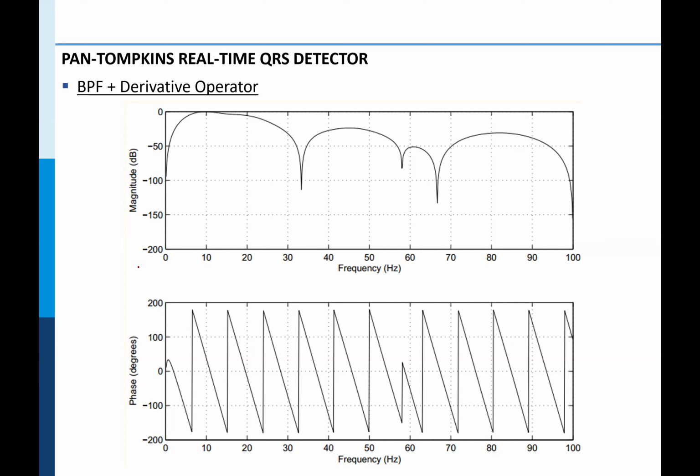Okay? So here, yes, the bandpass filter was cascaded with low pass and high pass. Then we had a derivative filter. So basically here, 3 digital filters are in series or in cascade. Okay? And when we put all of them together, we can always get even one transfer function that combines all the 3 filters, because they're all additive operations. It's a simple linear operation. Okay? So that's what we are noticing here.